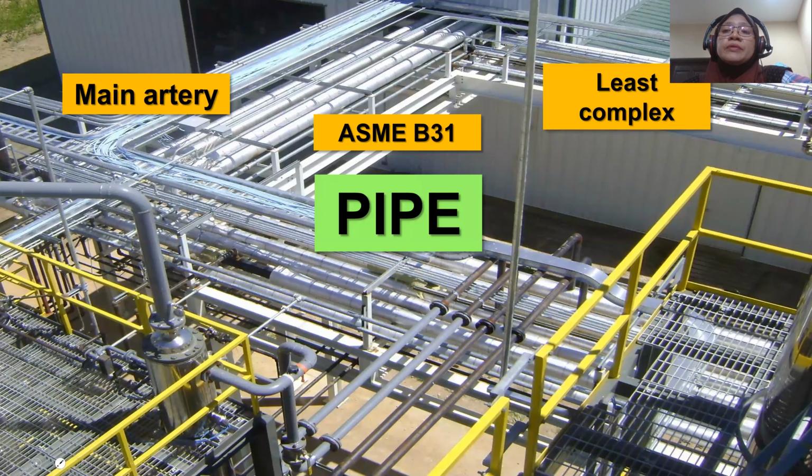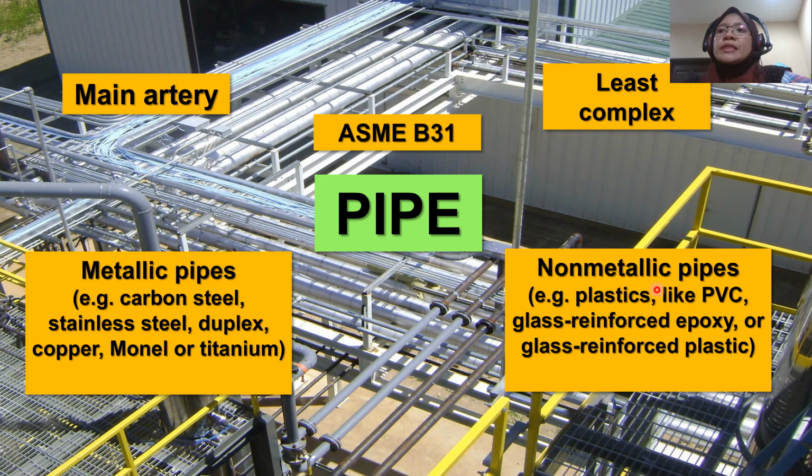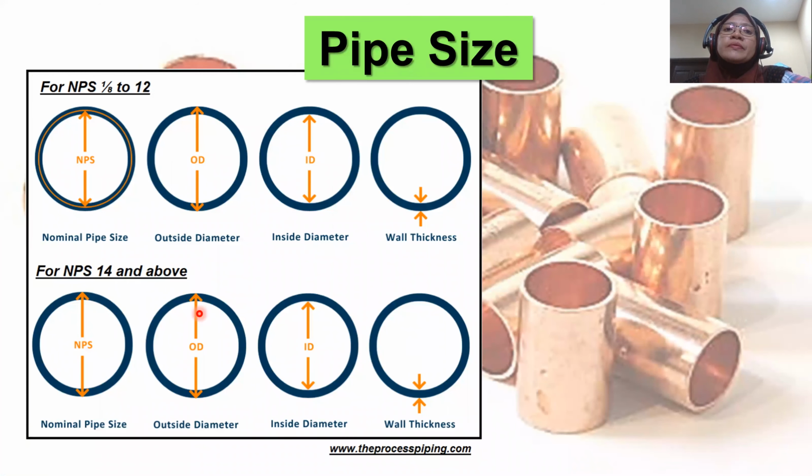And pipe is generally made from metal, for example, carbon steel, stainless steel, duplex, copper, or to a lesser degree, one of the more exotic metals like Monel or titanium. There are also pipes made from non-metallic materials such as plastic like PVC, glass reinforced epoxy, or glass reinforced plastic. The way pipe is identified is by pipe sizing terminology.